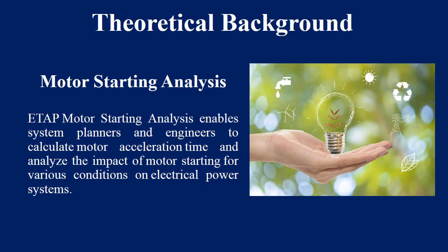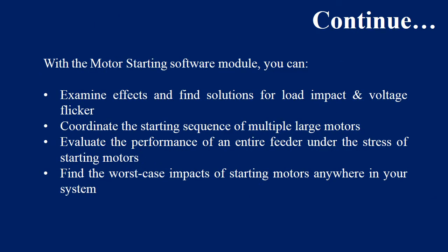What is motor starting analysis? ETAP motor starting analysis enables system planners and engineers to calculate motor acceleration time and analyze the impact of motor starting for various conditions on electrical power system. With the motor starting software module, you can examine effects and find solutions for load impact and voltage flickers.